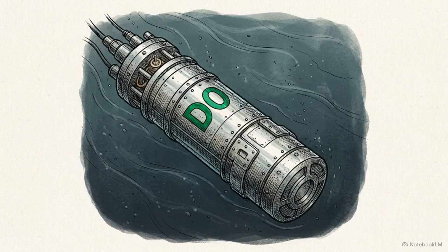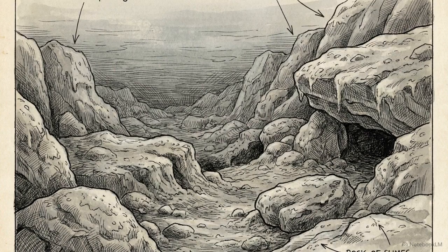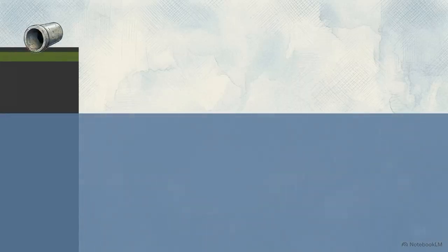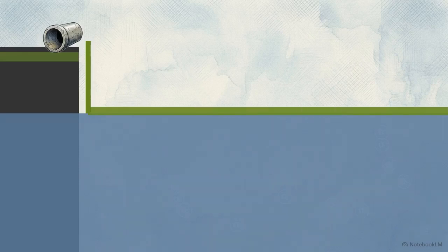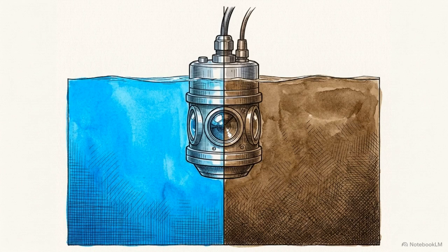Alongside the CTD, dissolved oxygen, or DO sensors, target a critical ecological threshold. DO sensors detect hypoxia, alerting scientists to expanding dead zones. These low oxygen areas are routinely triggered by eutrophication, where excess nutrients from agricultural or sewage runoff consume the available oxygen. Nephelometers, more commonly known as turbidity sensors, are deployed to measure water clarity.